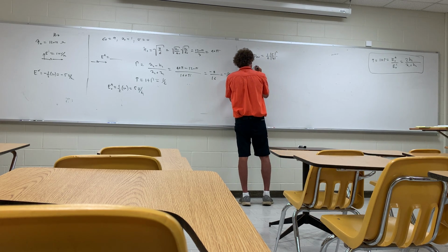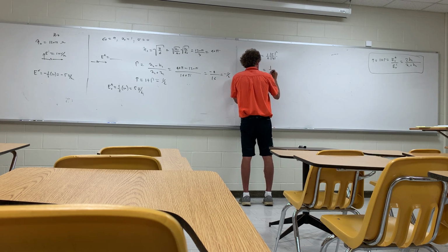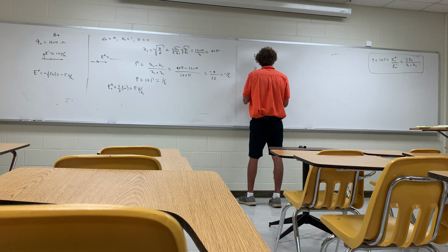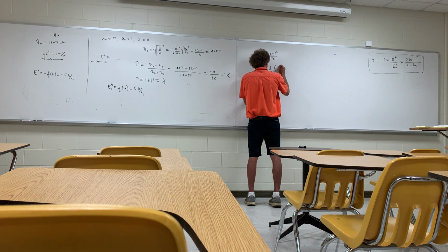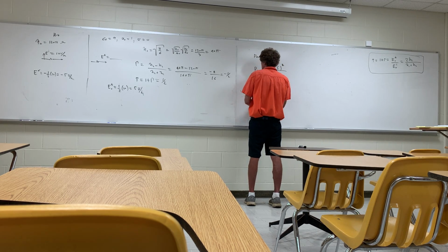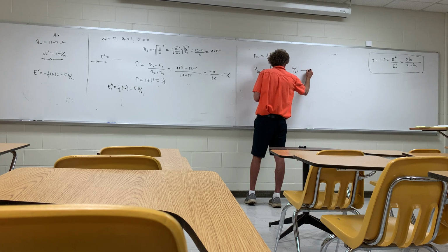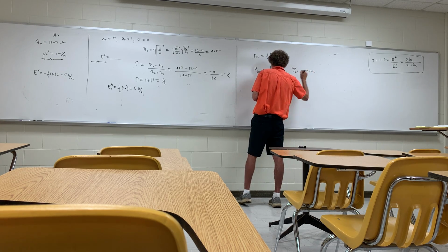So if we take a look at the transmitted power, P transmitted, this is power density really, it would be 1/2 the magnitude of the field transmitted. Well, that's 5 volts per meter, but it's squared, right? Divided by 40 pi. That would be watts per meter squared, and it would be going in the positive a_z direction.